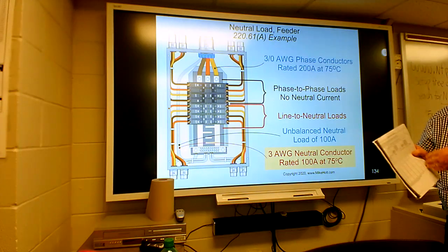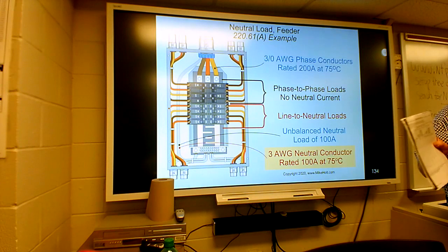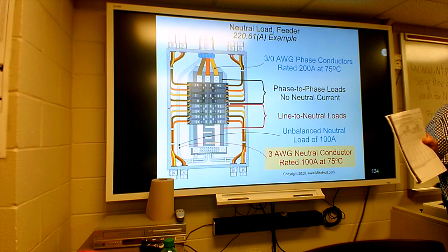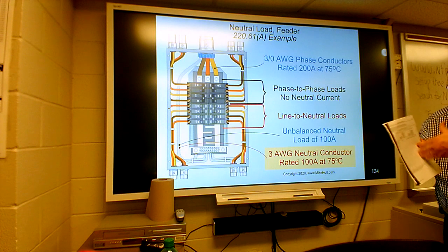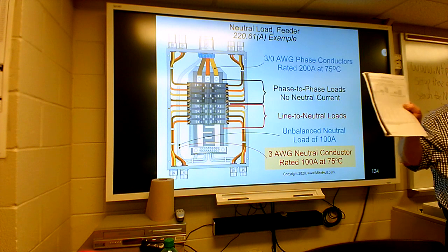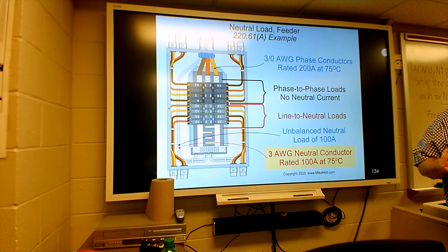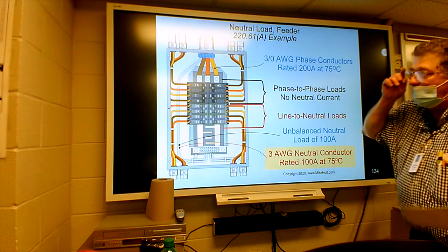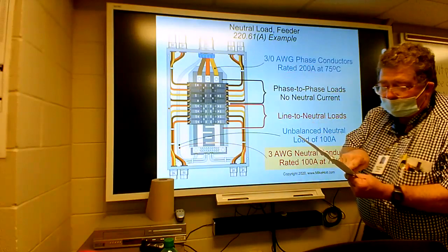Okay, there's 6 columns there. Out of the 6 columns, which 3 columns do we not want to be dealing with? The ones on the right, because it's aluminum or a copper-aluminum mix. So you stay on the first 3 on the left, which are just copper wire. And it would be the second column, for 75 degrees Celsius. And you're talking 200 amp.